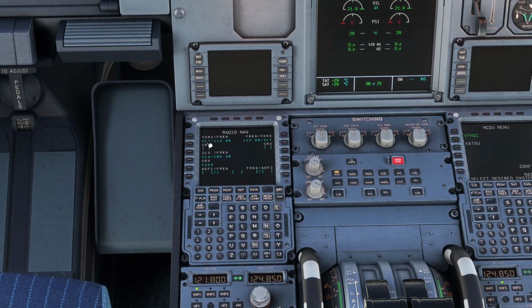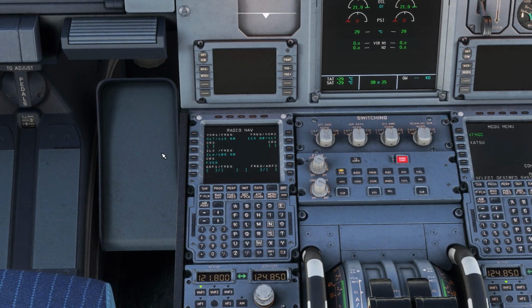So it's actually not a waypoint in the air, which is the RNAV navigation, or area navigation, if to be precise. But in this flight plan, there is also a VOR, which is a ground-based navigation aid. So this flight plan is a combination of the airways in the air, using the GPS coordinates, plus the ground-based navigation instruments. You can ignore this, and for the ILS frequency, you can see 109.90